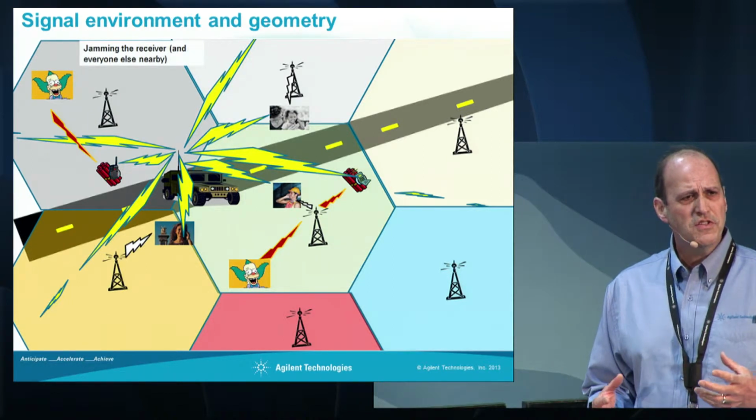Generally speaking, most of these signals that might be used perhaps to detonate an IED would be kind of in the 0 to 6 gigahertz frequency range. It's much, much less common for, say, microwave signals to be used for these purposes. So the idea is to try to look in all directions. Generally these would be omnidirectional kind of systems that you might use to jam, since the signal could come from any direction. And you're obviously trying to do the best job you can to evaluate as many signals as possible and act very quickly to be effective.